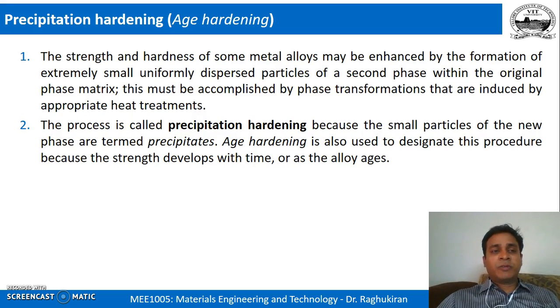Let us now first see what is precipitation hardening. We know any solid solution, right? You give any two elements, you have a predetermined, constant amount of B that can go into solution A. If you try to put more and more of B into A than what it can take, we call it a supersaturated solid solution, right?